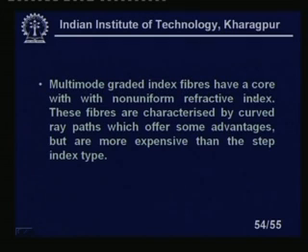So, multimode graded index fibers have a core with non-uniform refractive index. These fibers are characterized by curved ray paths, which offer some advantages, but are more expensive than the step index type. In lesson 29 we will cover this in more detail, including the passive principle and the incident light, and then we will go to some fiber optic based sensors. With this we come to the end of lesson 28 of industrial instrumentation.